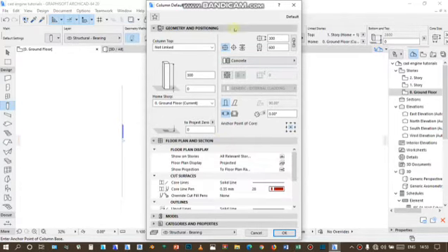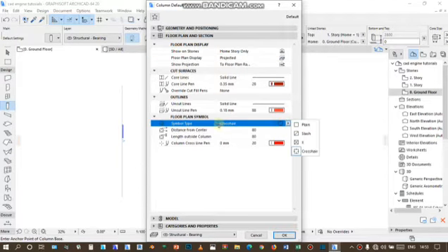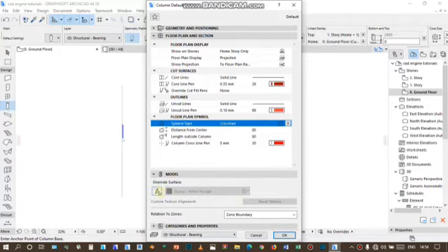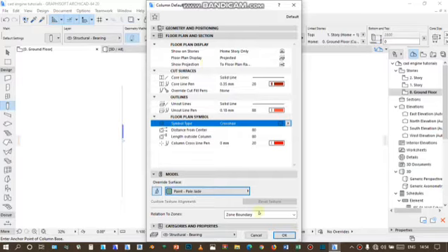This is where you set the floor plan, how it is going to appear on the floor plan, whether you want it to appear in all the stories or in the home story only. We'll be needing that information when we'll be designing a full tutorial, but for now let us just handle the tools first. Now you can change the symbol type to plain, slash, or X, or crosshair. Any one that you choose. Let us just leave it at crosshair. And here you change the color of the surface of the column. Let's just leave it at paint jade.